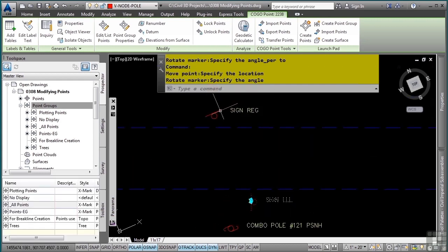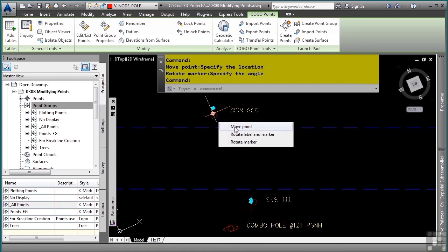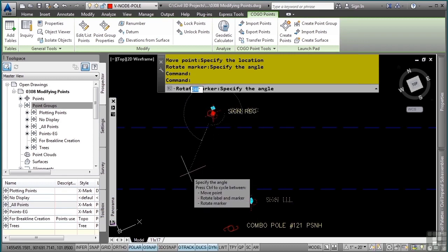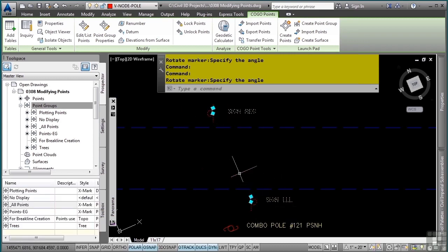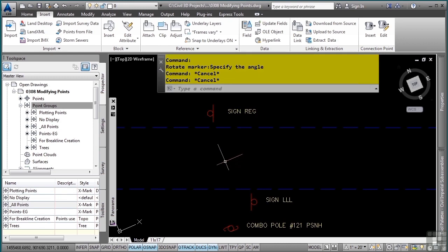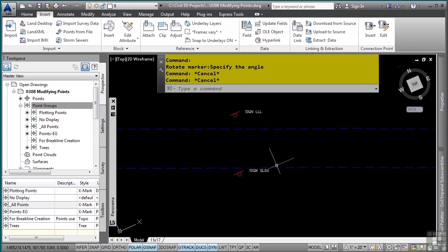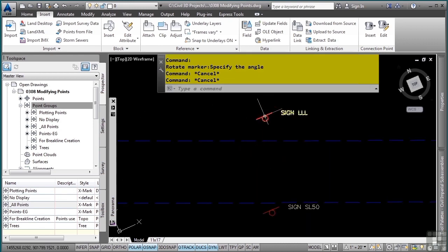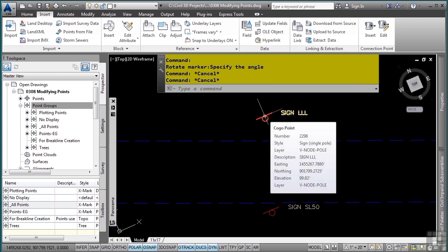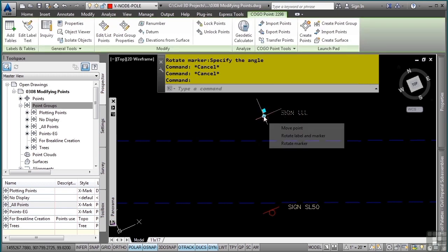Again, I can select multiple, rotate marker, and it's just going to use that one there because I haven't made that one a hot grip. So as you can see, it's very easy to set up Civil 3D to minimize your view for the specific points you want to see, as well as rotating just your points and not the...